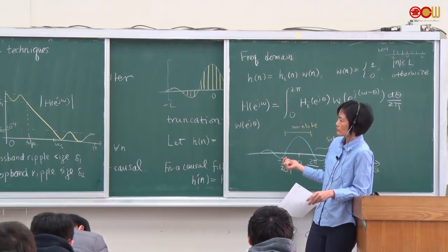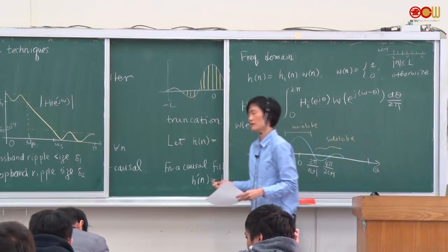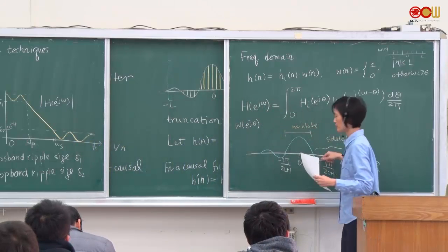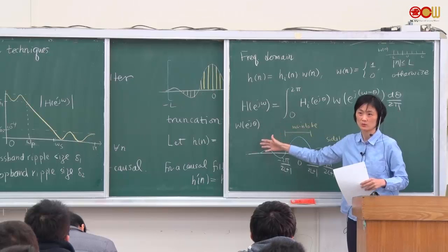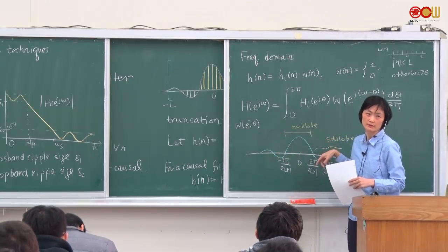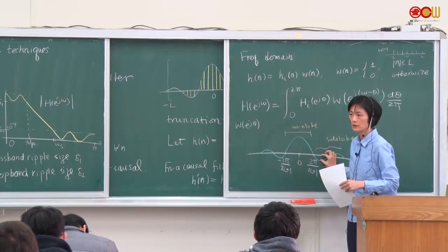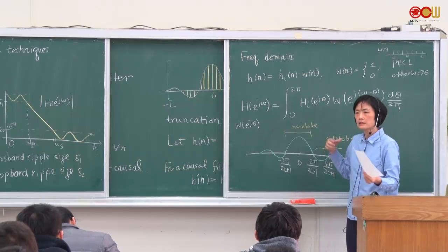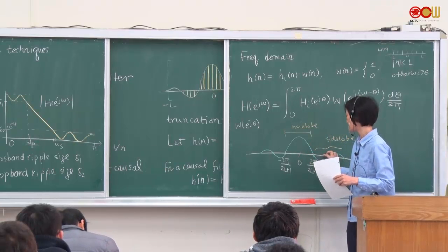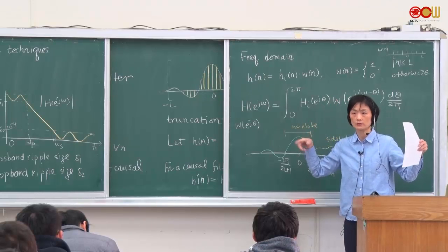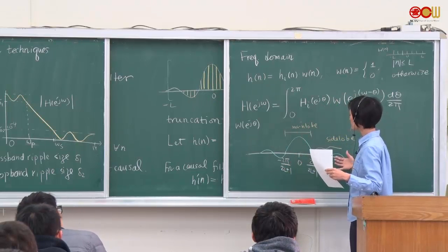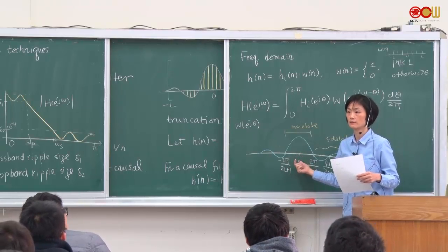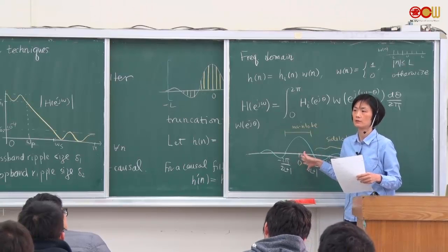So, we know the window function is always the rectangular window, right? The frequency response always looks like this, and this slope is kind of fixed. There's no control over this side lobe because the rectangular window function is a fixed function. So in the frequency domain, what we will get would be a fixed thing. If L is fixed, then everything is fixed already.